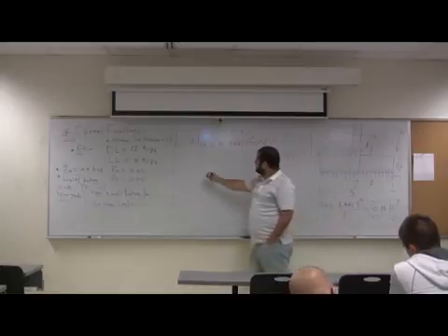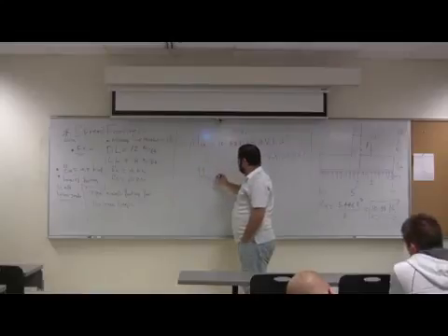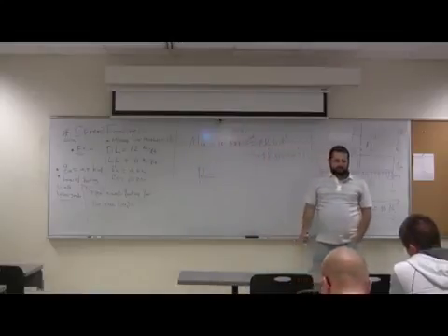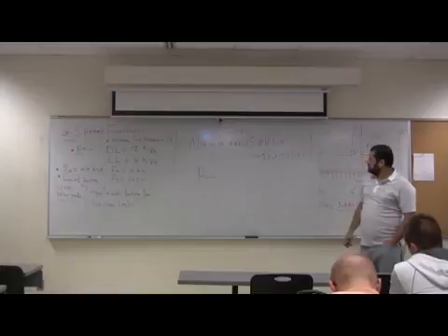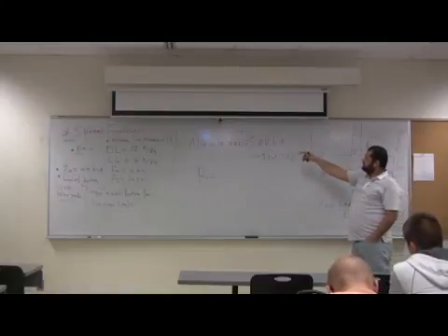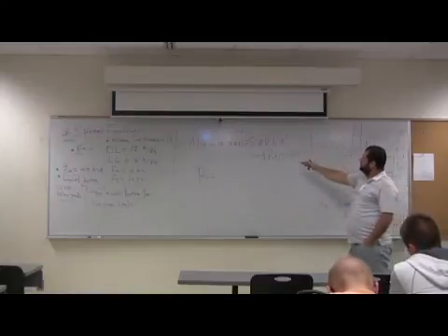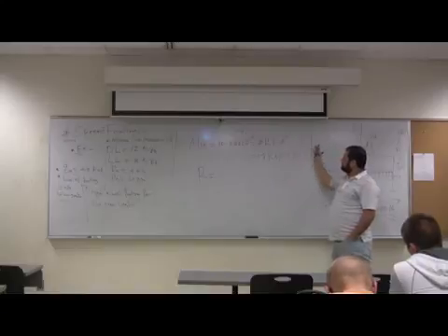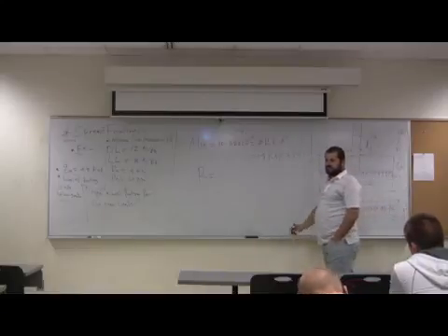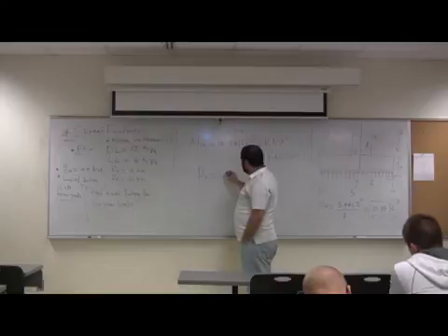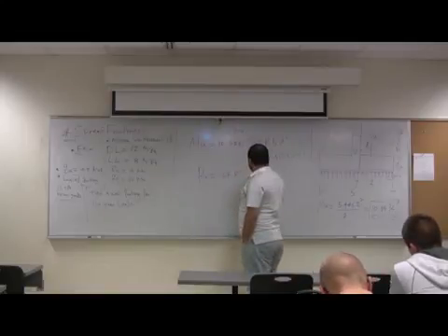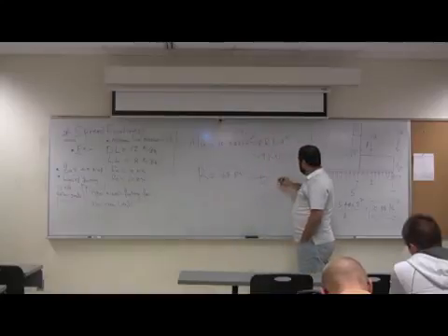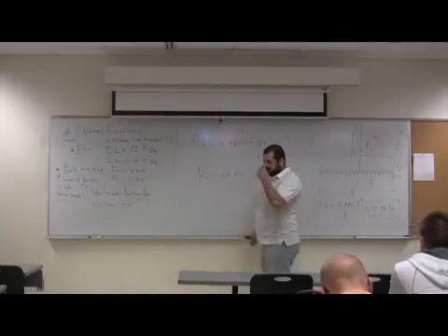You do that, you will get R equal 10.88 times 12,000 divided by 0.9 times 12 times 8.5 squared. You get 167 psi. Go to the design aid and get me rho for that.